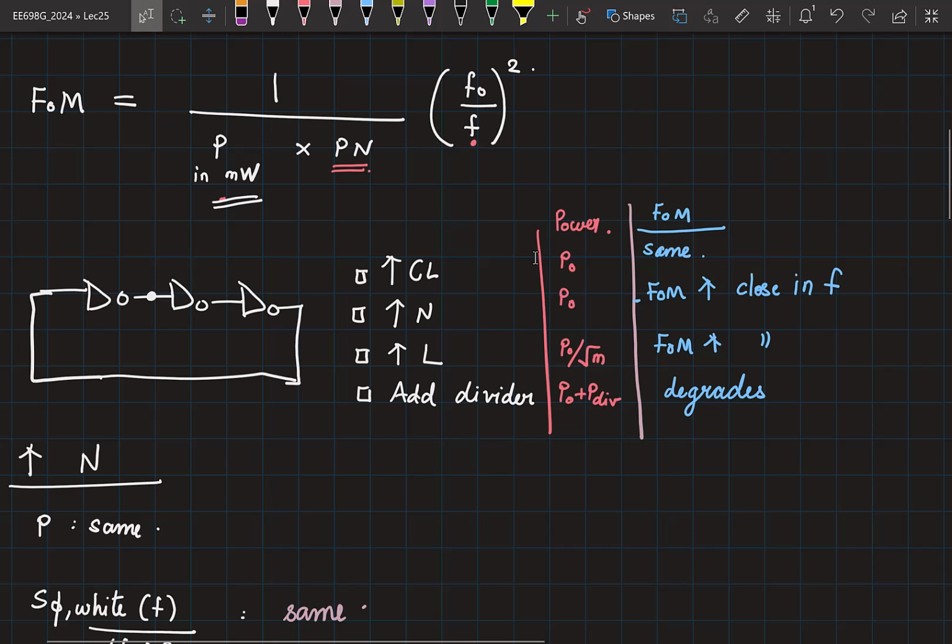If you are increasing the length to get a lower frequency but with 3 stages, then at each stage the signals are taking a lot more time to rise and fall. So it's going to be a very distorted waveform, which means you are probably going to burn a little power in the buffer following that. Now if you increase the n, you'll have better rise and fall times. So something to consider. These are trade-offs that you will know once you start implementing, and then you will make a decision. It is going to look more like a sine wave.